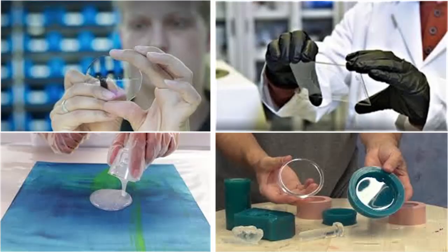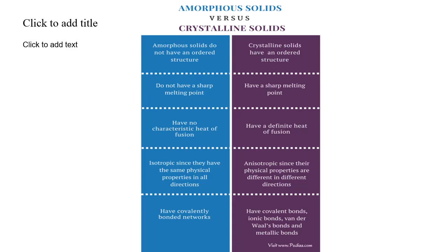That's why amorphous materials are widely used in applications such as optical lenses, coatings, and adhesives, where flexibility and tunability are more important than rigid structure. While crystalline materials offer strength, stability, and precise performance, amorphous materials provide versatility, transparency, and adaptability. Understanding this distinction is essential when selecting materials for adhesives, coatings, and fillers like silica in epoxy formulations.